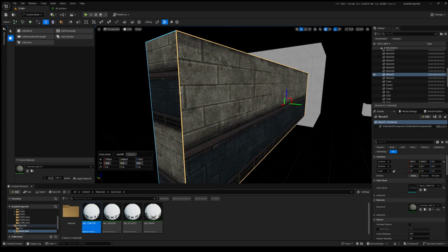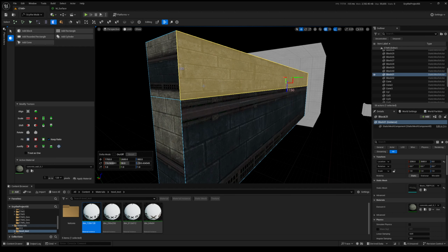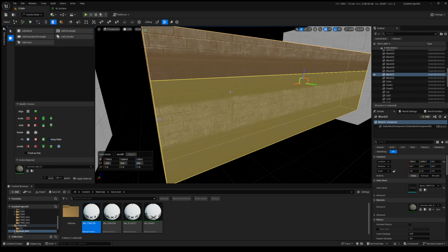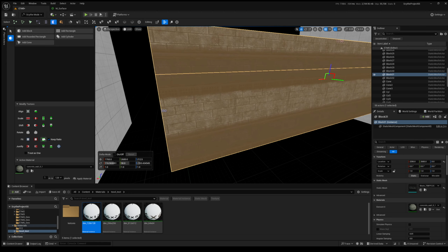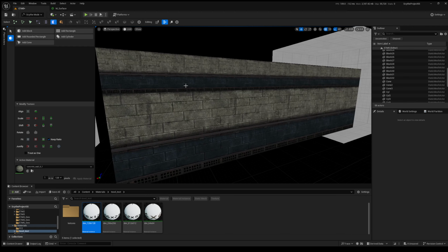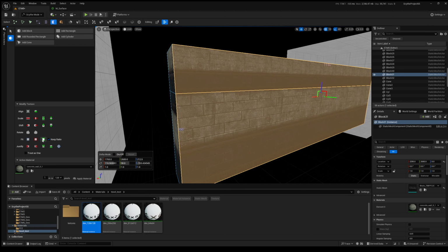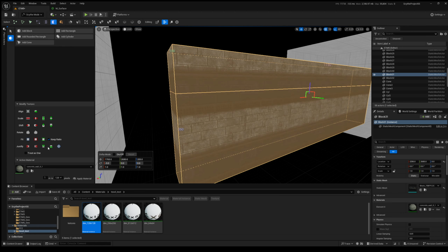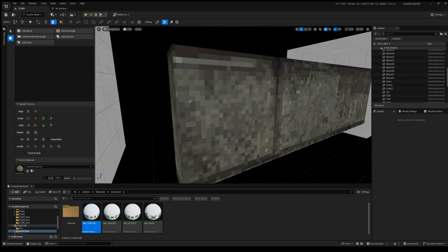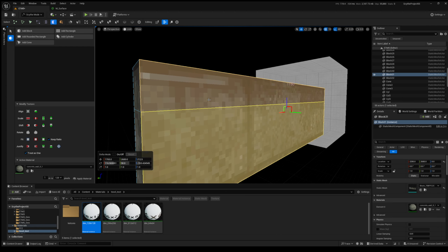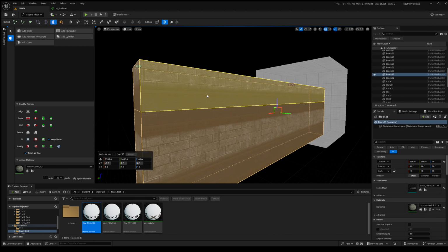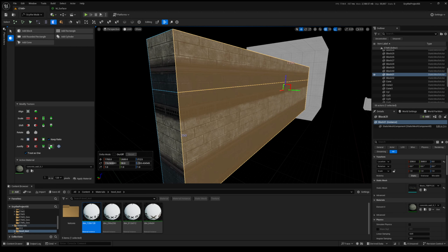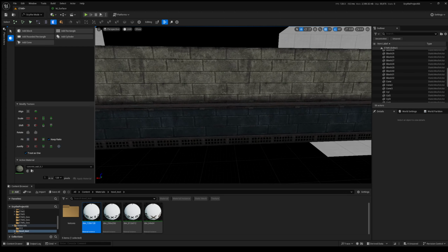And then if I were to chop this up a little bit, and then align to the grid again, and then I'm like, oh, okay, well, I want to do that for that wall. It's like, oh, that doesn't look right. What's going on? It's because it's doing this for each face separately. So I'm going to reset that. I'm going to treat as one, and then, oops, I have too much selected. We'll do that. We will treat as one, and look at that. They're both done.